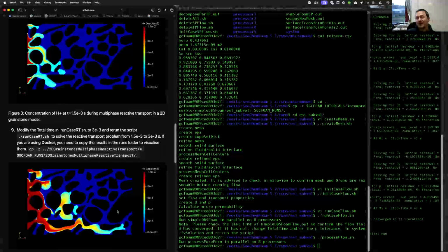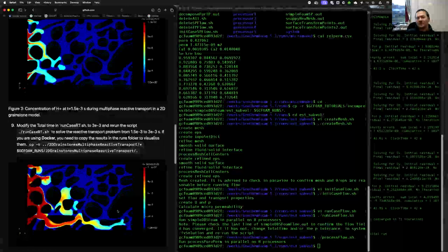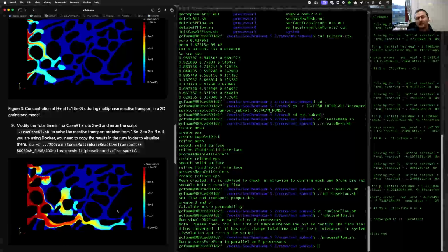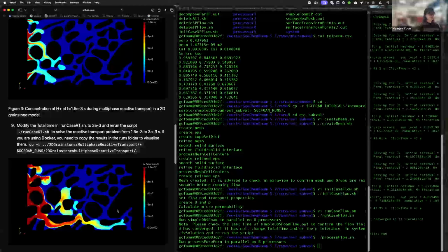But in this particular example, the interface is blocked, but you can change it. Because this is oil and water, H+ is not going inside the oil, but there's a parameter that you choose, which is put at 0 now, and if you don't put it to 0, it will go into the water, which is what you want to do. So you want to look at this tutorial. Thank you.